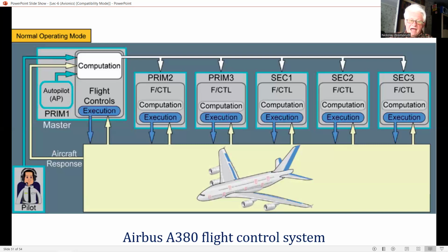An electrical backup system provides control of the aircraft in the extremely improbable case of loss of all the flight control computers or electrical power supplies. The electrical backup system is totally segregated from the normal flight control system and uses dedicated sensors and transducers in the pilot control.